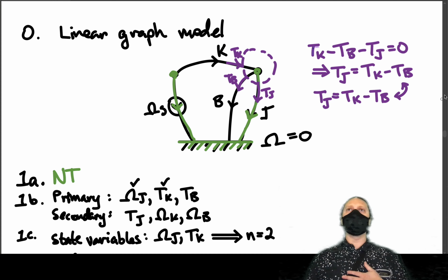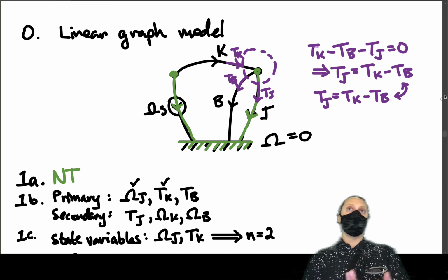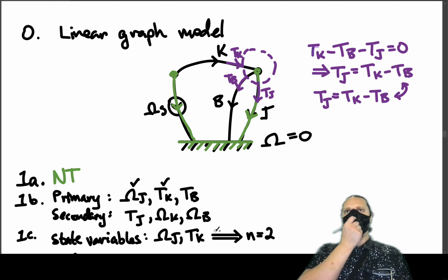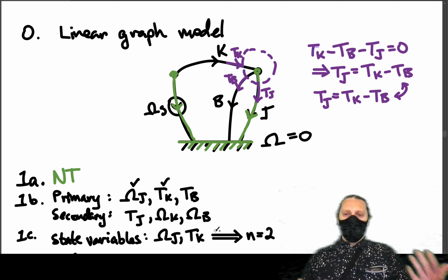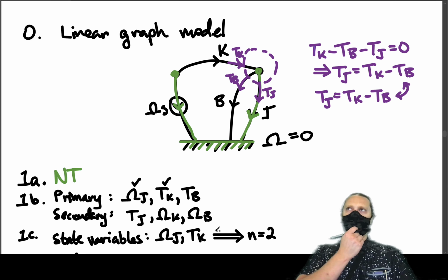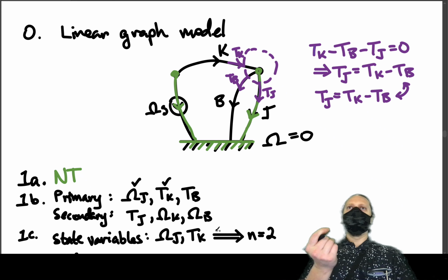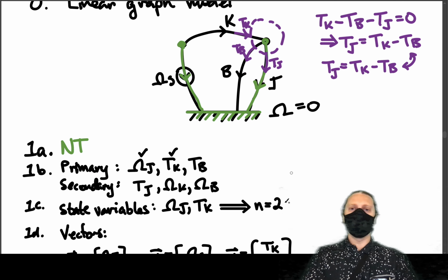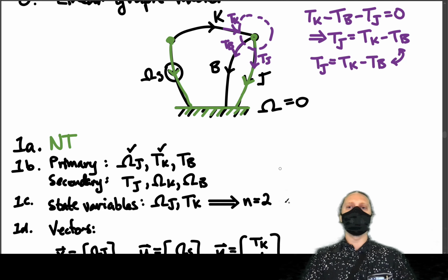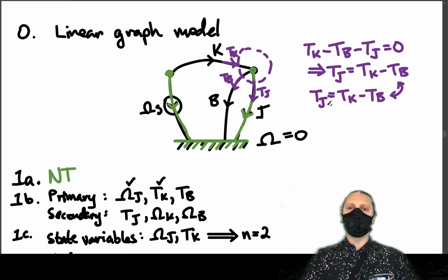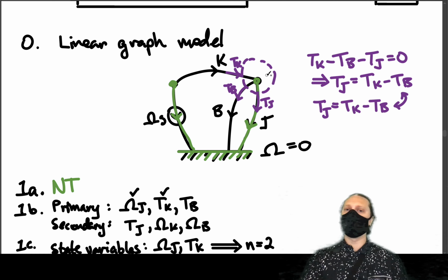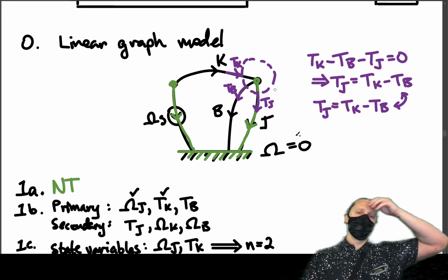And in fact, if you really buy into using this shortcut and the next shortcut that we talk about, you can actually skip writing the primary and secondary variables, which I find to be nice. But again, it's whatever you're comfortable with. Don't sacrifice accuracy for speed here. The shortcut's not great if you're not super comfortable with it. So if you ever get confused, if you don't remember how to use this sort of reasoning with the shortcut, you can always go back to just summing everything that goes into the contour and you're good.